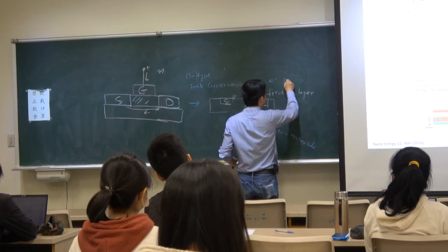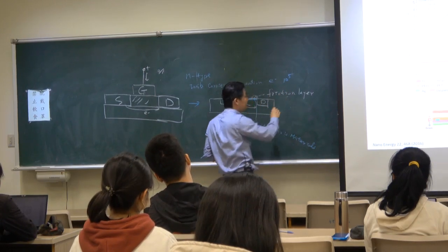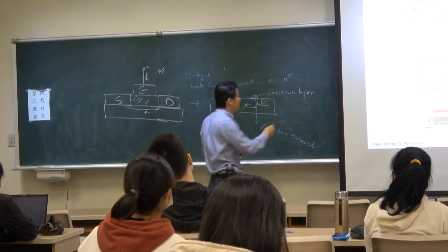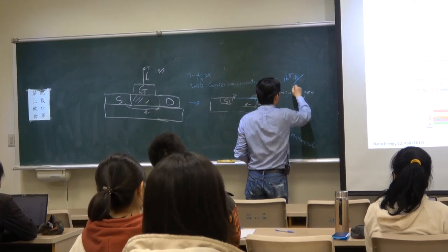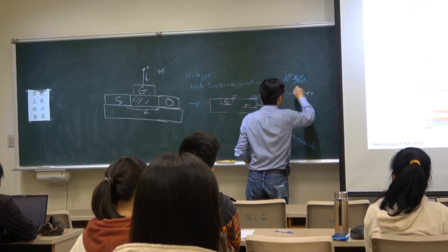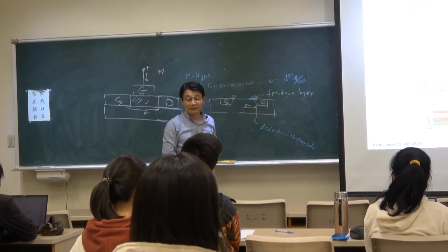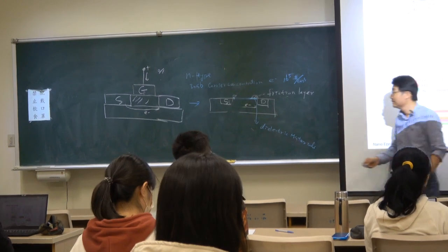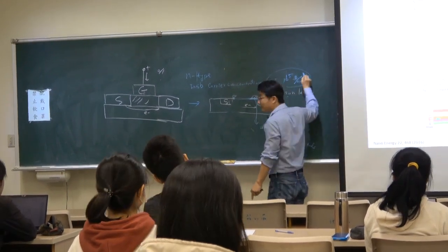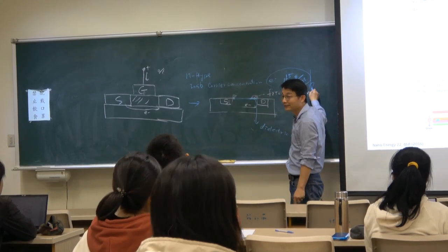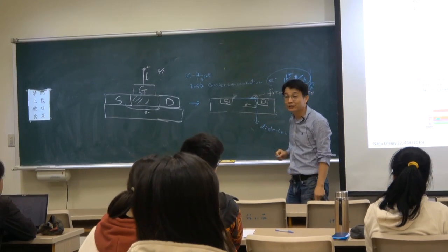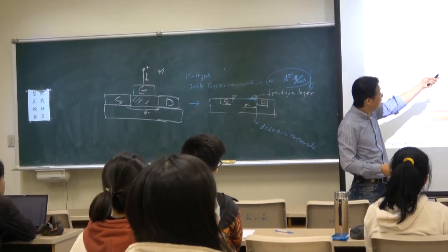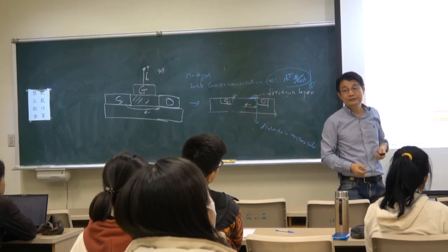Then I have, for example, just any number, 10 to the 5, per cm cubed, right? And then because electrons flow out, the carrier concentration will be dropped, right? Is that okay? Carrier concentration will be dropped. So the carrier concentration being dropped, the IDS will be reduced, right?